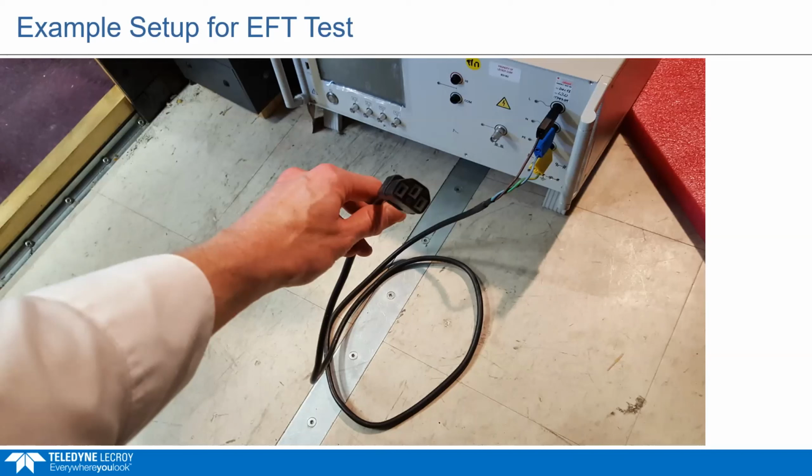So I just took a picture where I'm holding the power cord. And normally a device that's being tested for EFT, you would hook it up to the power cord where it's including EFT into the power line itself. But before the EFT test is done, it first needs to get tested on an oscilloscope. And so you capture the EFT pulse coming out of the generator, make sure it meets all the requirements, and then do the EFT testing in the lab.